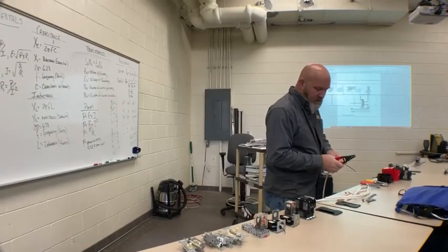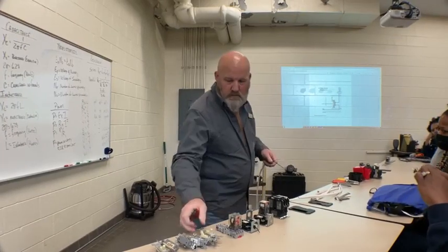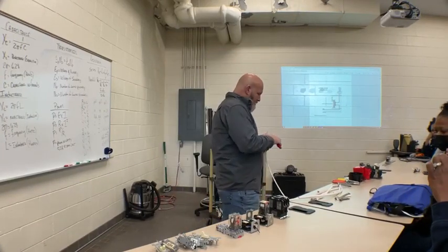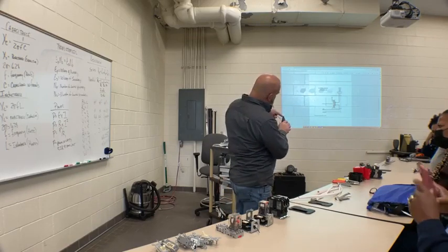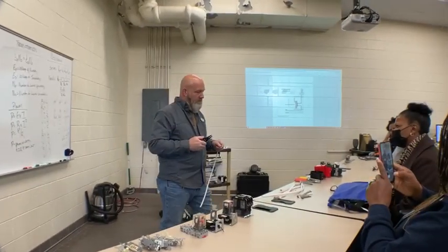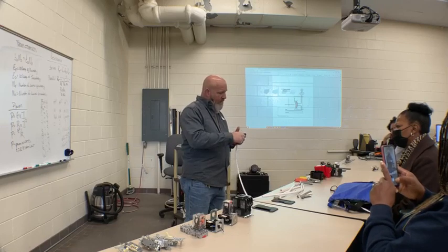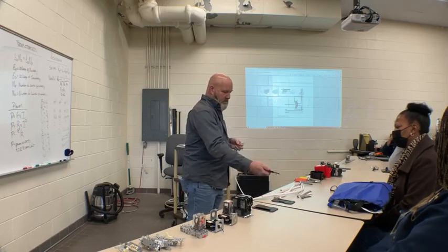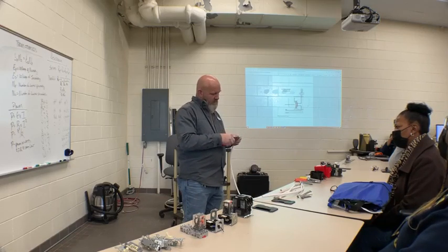And what y'all are going to get practice on today is putting the wire on a single pole switch. These are wire strippers. They have numbers on them for different gauges of wire. This is a 14 gauge. So you put it on where 14's at, about 3/4 of an inch, and then push it off. And that little piece falls on the ground. 3/4 of an inch, push it off.